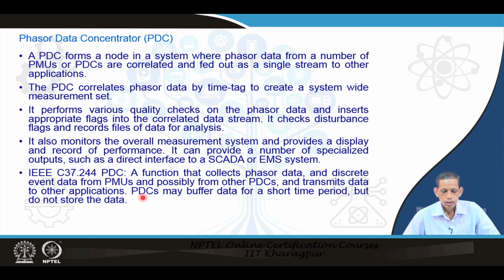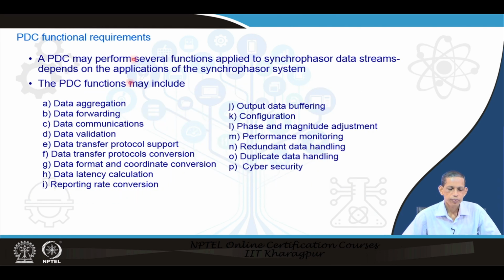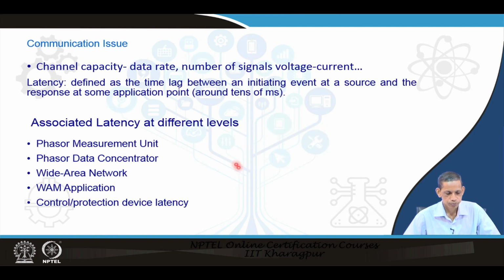PDC may buffer data for a short time period, but does not store the data. The purpose of PDC is not to store data. PDC functionality can be of several kinds: data aggregation, data forwarding, data communications, data validation, all related to data reporting, rate conversions, output data conversion, redundant data handling, and even the cyber security perspective, because these involve communication systems and the associated computer technology.